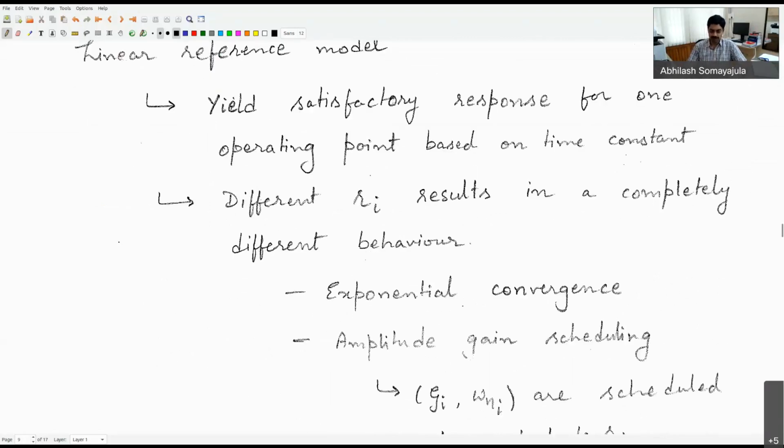This is a very good way to go about it because it's very simple to implement and it doesn't take a lot of overhead. So if I'm actually implementing on a small craft like my scaled model, I might not be too worried about the computational aspects related with a simple filter like this. It'll be pretty straightforward to do the computation. But rather, if I had a very nonlinear filter or nonlinear way to figure out what the desired trajectory would be, then I'll be adding computational overhead onto my machine. Right? For very large ships where you can have a real good computer on board, then these may not be a big issue.